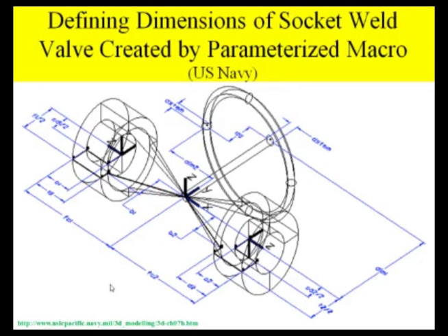Now look here, it has an origin in the center of the valve, and then it has two connection points on either side. It's a two-port device, and they have out vectors. Here's where to connect, and here's my out direction. And so if I connect it to another flange pipe or a pipe, actually this is a socket welded valve, so if I connect it to another pipe, then the connection points have to be shared and the out vectors have to align. And the way to generate this, they just have an outline and they sweep it, they spin it.